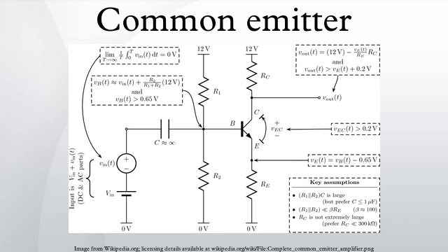Applications. Low frequency voltage amplifier. A typical example of the use of a common emitter amplifier is shown in Figure 3. The input capacitor C removes any constant component of the input, and the resistors R1 and R2 bias the transistor so that it will remain in active mode for the entire range of the input. The output is an inverted copy of the AC component of the input that has been amplified by the ratio RC/RE and shifted by an amount determined by all four resistors.